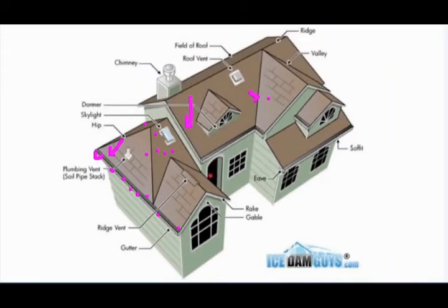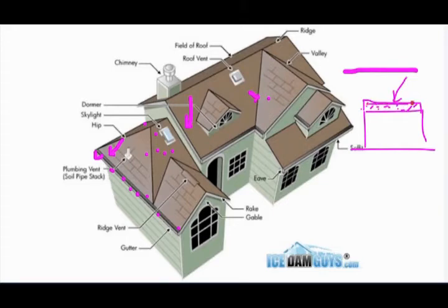But traditionally they have been using a flat roof. In Konya, in old days, while there was some snow on top of the building, the snow, first of all, worked as insulation. If there was very cold weather outside, this roof worked as insulation and did not let extra cold inside the building. The other reason I mentioned is that extra load on the roof will put pressure on the gable roof, which might easily break.